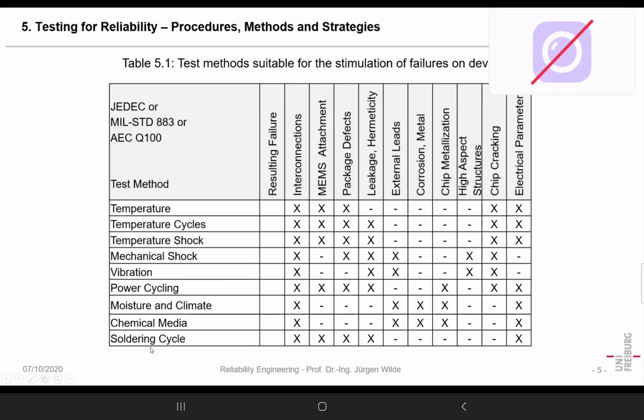And also what was found out is that for a device, it makes a difference if it's a device that is just tested or if it's a device that was soldered previously before testing. And normally in equipment, especially at that time, one had to assume that every soldered equipment is soldered at least twice. The reason is that often at that time, because electronics were very expensive, we had rework.